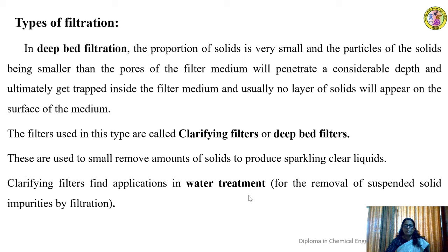In fact, they are found useful in the treatment of water to remove a small quantity of finely divided suspended solid impurities by filtration. The sand filter is one which acts as a deep bed filter. So this is an example of deep bed filtration.